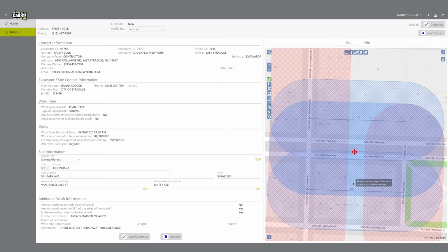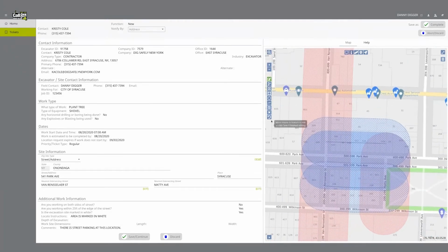By clicking within the now gridded dig site area, you can move the area entirely. When you click, hold and drag the area to your desired location. You can use the Cancel Discard button to go back to your original dig site. If at any time you need to erase a step you have taken while using the Edit Dig Site tool, click on the Undo button.